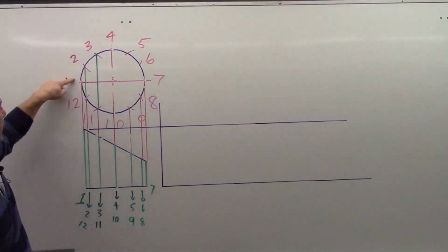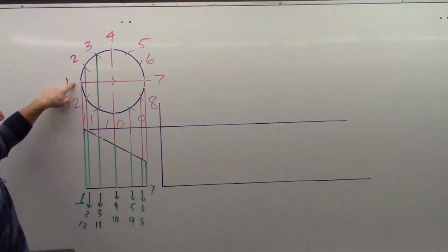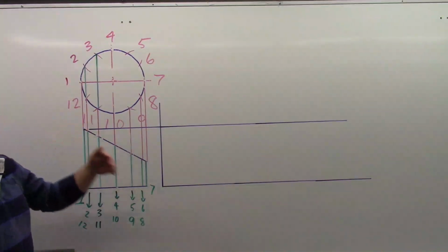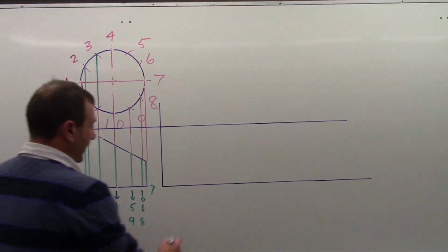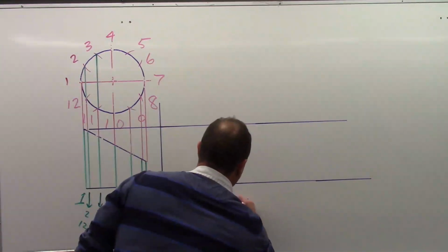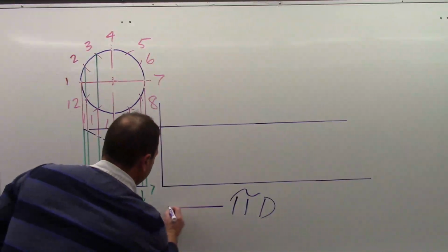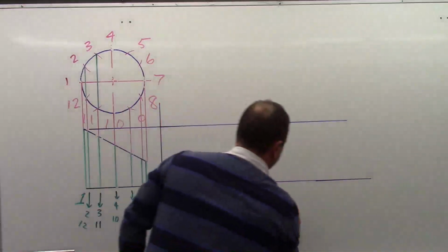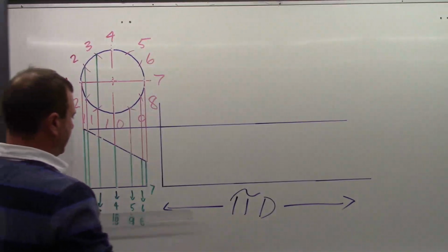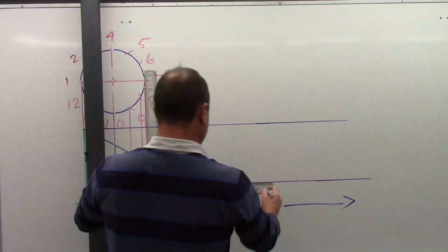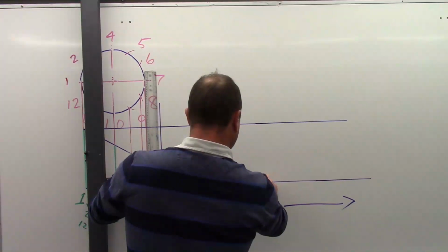So how much does it take to go from 1 all the way around and back to 1? That's what we refer to as perimeter, or in this case a circle, it's called circumference. And our calculation for circumference is pi times diameter. That will be our stretch out. In this case, I'm going to mark halfway first because it's quite long.